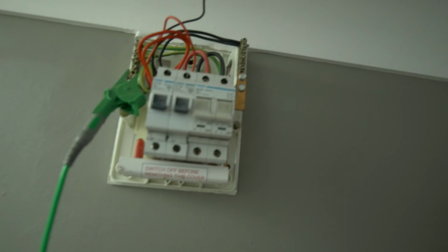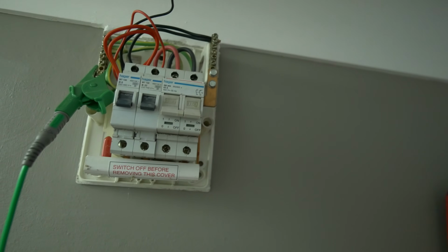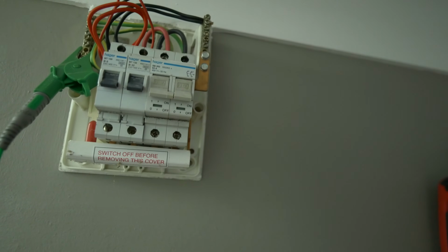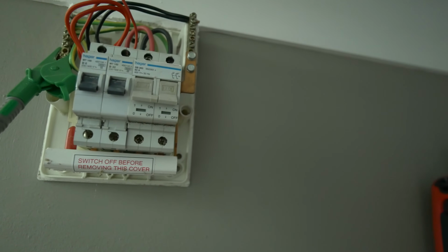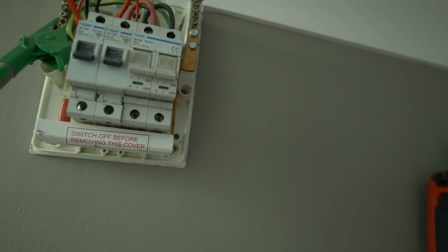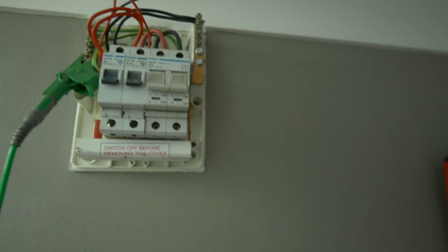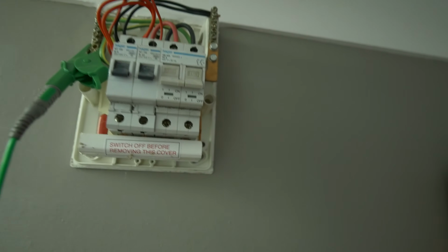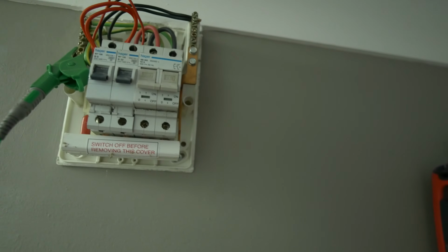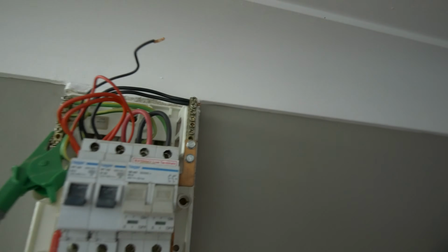And you need to remember, with this being an EICR and not initial verification, you take the level of testing to where you see fit as the inspector, based on your visual assessment and how you see the results you're observing. So if you are all clear at 250 volts, it's a small install and you're happy, you can leave it at that should you wish, as long as you note the tests you've taken and the reasons why you've taken them. You'll note here I've popped the neutral out for the lighting circuit.